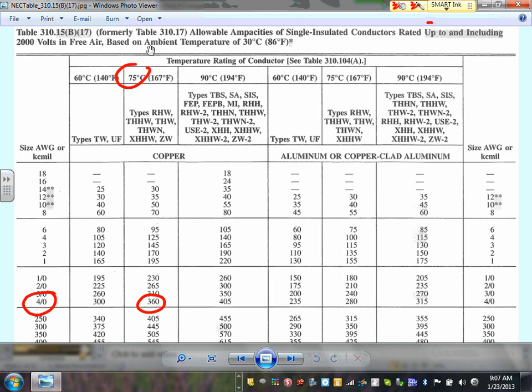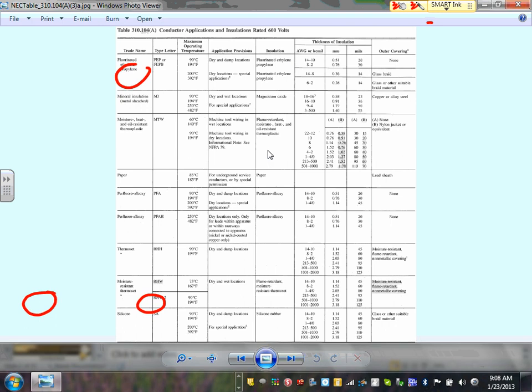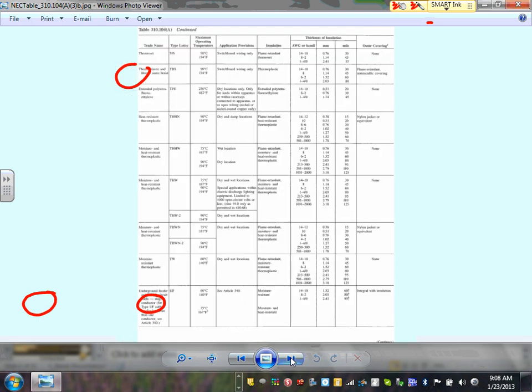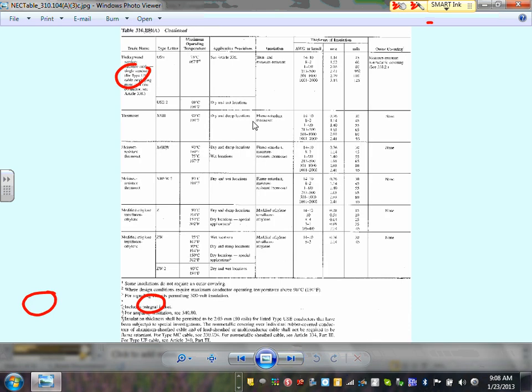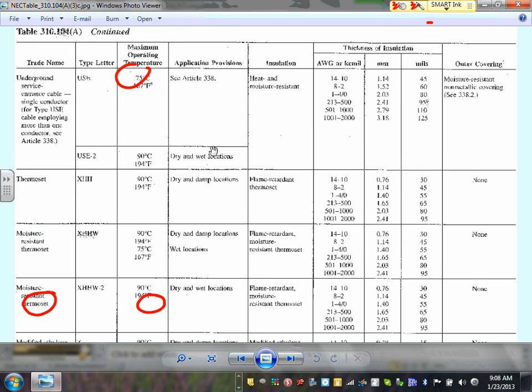So that will give you an idea why Xcel, when they put all their power lines, they don't put insulation on them. Bringing power from Becker all the way to Minneapolis, completely bare, naked up in the air, so they can be cooled, right? A day like this, when it's cold, it's perfect for the conductors. A cold day. So that table is really nice to compare and see how you can do that. Got the conductors, ampacity here. So these are the things I would like guys to quickly emphasize.